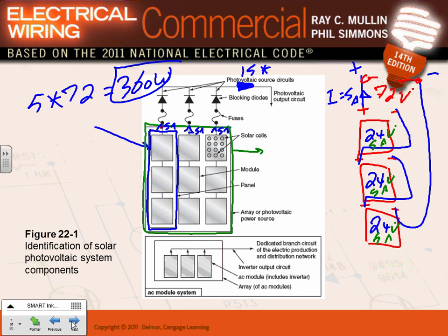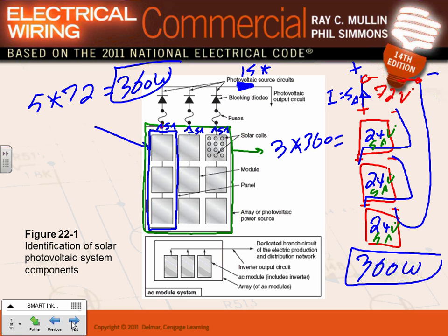So with each one of them you get 360 watt. You take 3 of them, right? What's 3 times 360? 1080 watt. Thank you. So this plant is 1 kW. If you take this one and multiply it by 72, can you guys check if you get 1080 watt out of that? So that's how much watt, 1K. This plant will give you 1 kW DC.